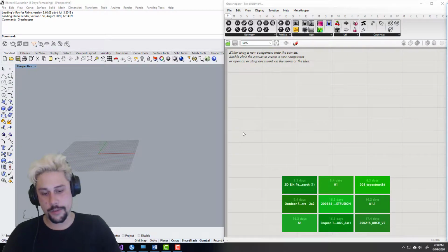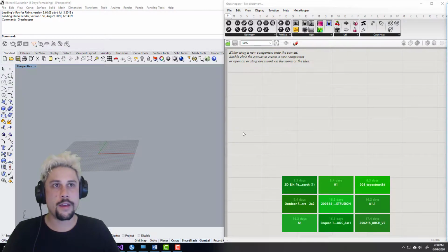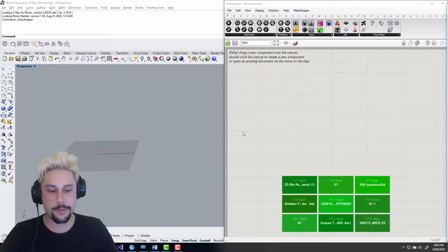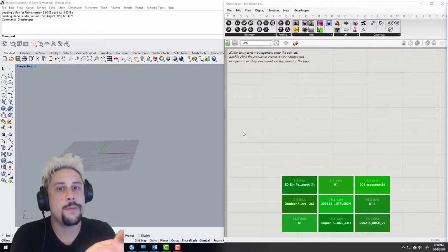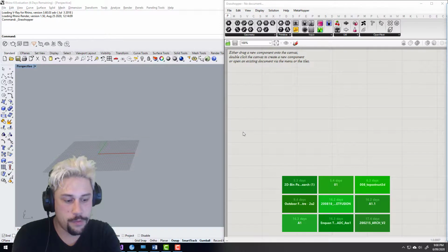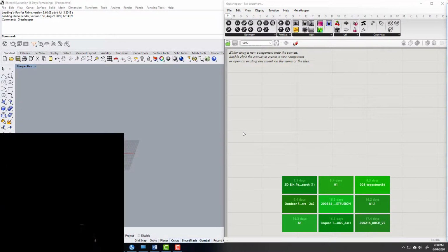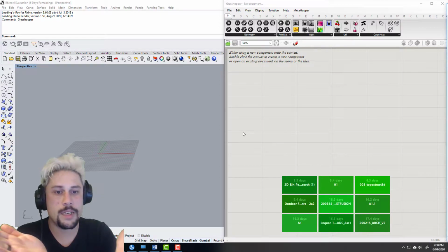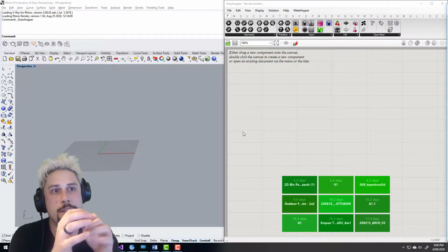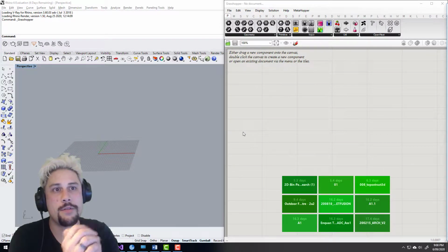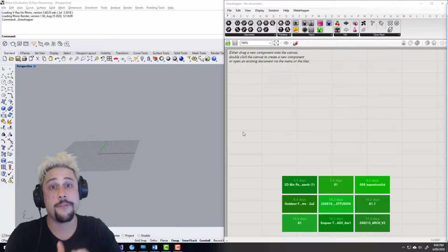Tonight I wanted to recap that Millipede workflow that we just got unwrapped out of the box and went with. So we'll do that again, pretty quickly. I'll cover a few other bases around that, and then I'm going to work on a very small project, which will be a bit of fun, but we'll use Millipede to do some initial form finding, and then we'll tidy that up a little bit and fill it with a bit of a structure that will generate, and then we'll chuck that into Grasshopper and have a look at how it performs.